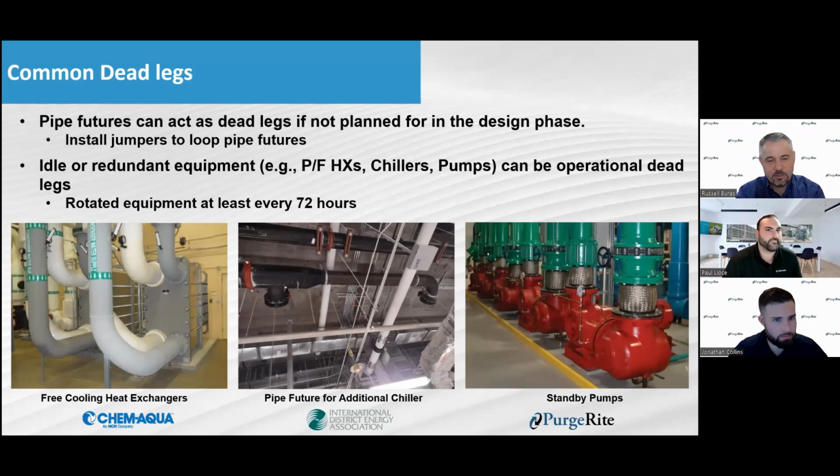Yeah, you're spot on with that. And this touches a little more on flushing. Just think logically: if you've got a long dead leg or future pipe and you're running debris down a channel, it spins off into that and you can't get out of it. So it is good to think about having some connectivity points in there. If you can circulate your chemistry, that's perfect. If not, keep it very, very short, no more than 2 times the diameter, which has been experimentally proven to be the worst case scenario. And then you may also want to add blowdowns during the flushing process.